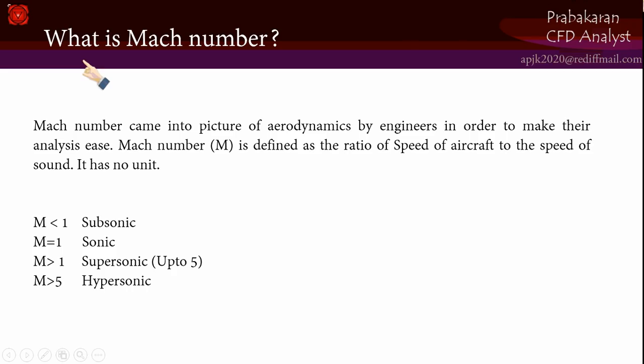So now it is our turn to turn our attention to Mach number. As an aeronautical engineer, we need to know the importance of Mach number, because we measure the velocity of aircraft in Mach number only. In flight we have special effects in the flow, like shock waves, and that is one key factor for the introduction of Mach number.